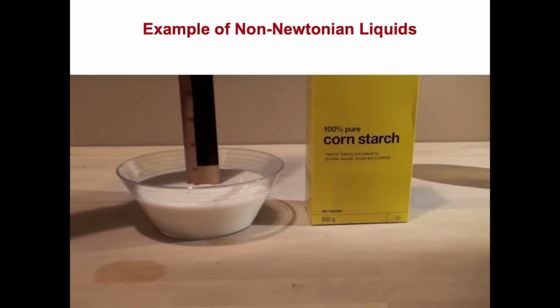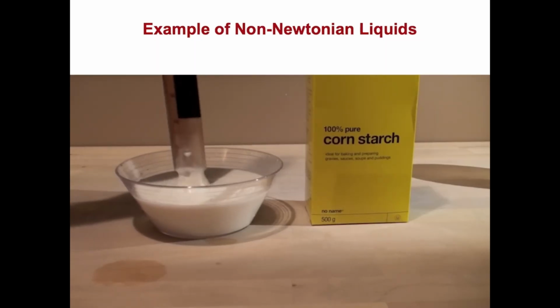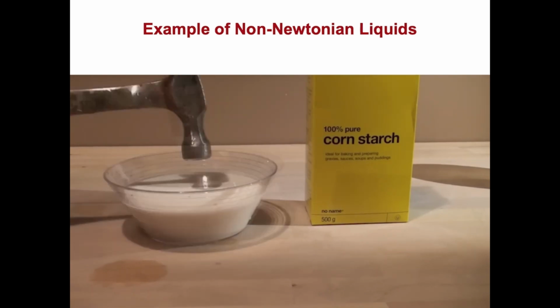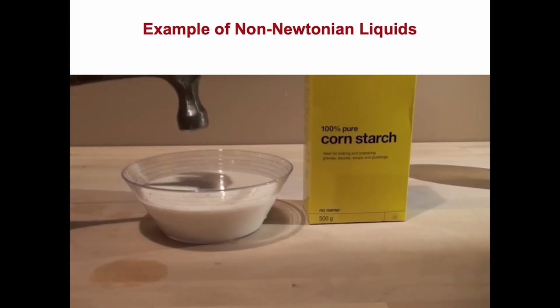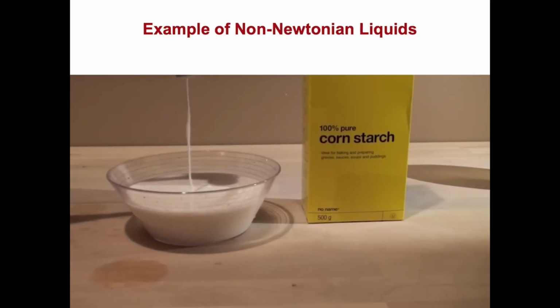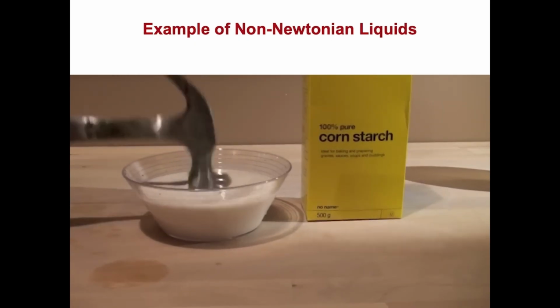But on the other hand, cornstarch is a non-Newtonian liquid. If you move your hand slowly in cornstarch, or put this ruler in slowly, or next he'll show the example of a hammer, it will enter and you can push it around as if it's a solid. But if he hits that ruler hard or quickly, essentially increasing the velocity gradient or shear stress or shear rate, he cannot push in, and the behavior of that liquid changes. It starts behaving like a solid.